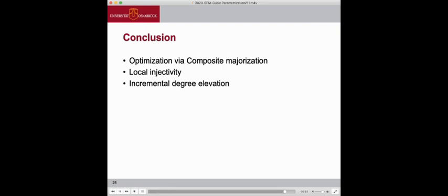And finally, we extended the idea of using a scaffold mesh for global injectivity by modifying it via edge flips and a conformal distortion objective. Our empirical focus herein was on demonstrating that abstract benefits in terms of lower distortion can be achieved using higher order parameterization. Further exploration of concrete practical advantages that result from this will certainly be of interest.